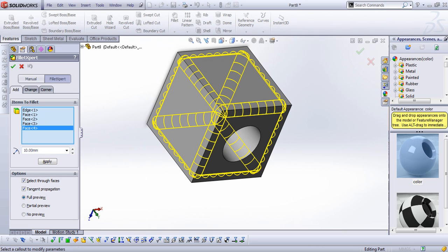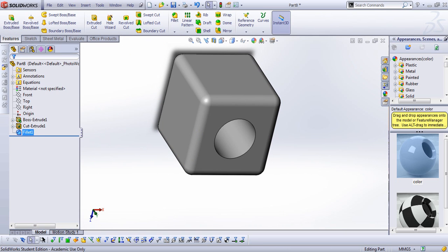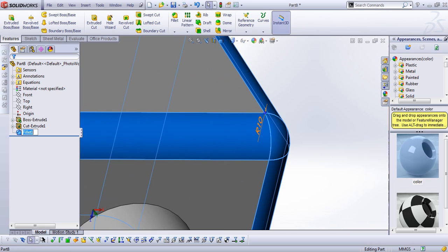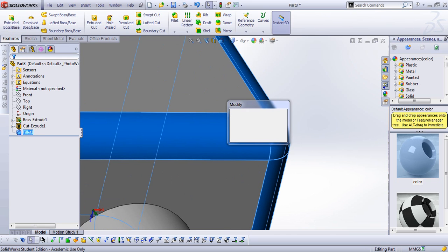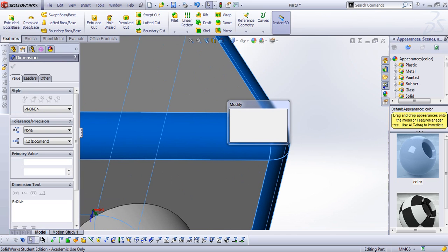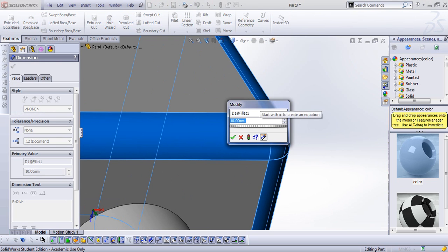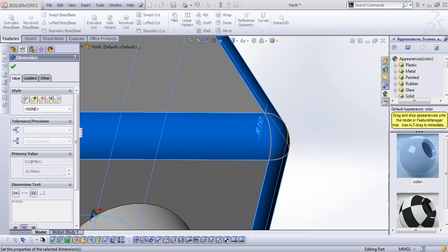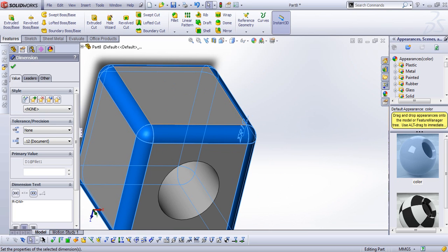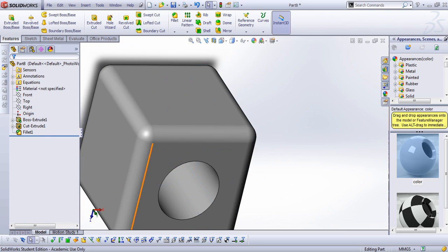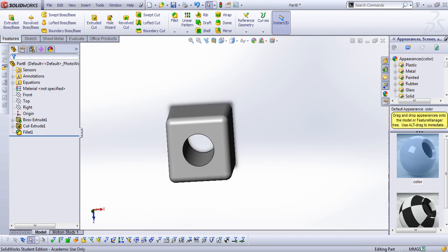And my fillet also here size 10, I change that to my global variable, equal to my last global variable, which is size 4. So here what I have is a geometry that has 4 global variables.